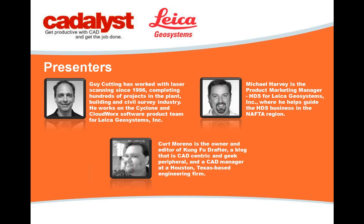So you can go into Cyclone, or you can go into a lot of the CloudWorks tools. CloudWorks are plugins for your CAD platform. We have one for AutoCAD, one for MicroStation, one for 3ds Max, one for Maya, one for Smart Plant Review, Smart Plant. We also have one for PDS, which is also MicroStation, and Revit. So we can get into all these platforms and you use what you want. You're going to use the workflows you're currently used to, and CloudWorks is going to help you put that point cloud in there and facilitate that.